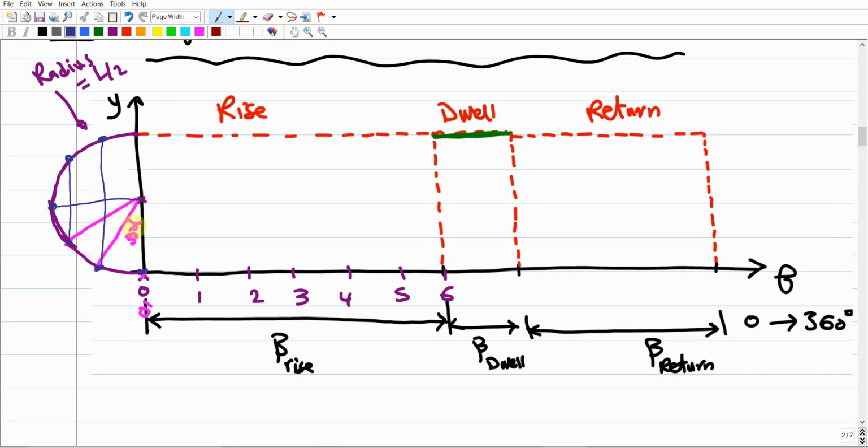This is because this angle is 30 degrees. This should be 30, this should be 30. Without measuring the 30 degrees one more time, you can just draw these vertical lines, and you're gonna end up with the other marks. So at the end, we got 6 marks: this is gonna be 1 dash, this is gonna be 2 dash, this is gonna be 3 dash, and 4 dash, and 5 dash, and this 6 dash.